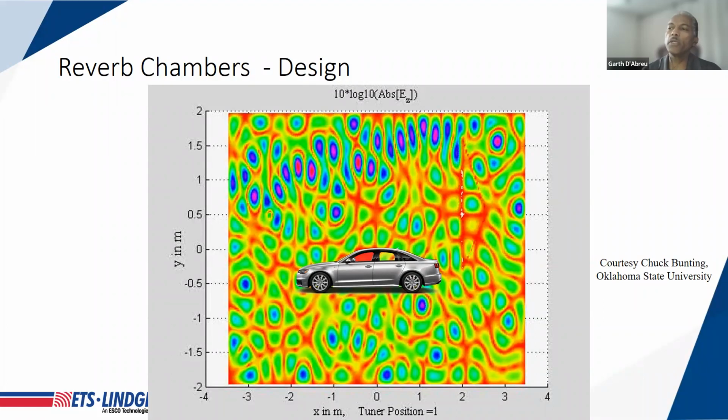If you've got a component that, when exposed to a particular level of RF, would only respond after some fixed duration, or past the expiration of some fixed duration, then that introduces a dwell time to the measurement. And if you're testing in a reverb, it's a little more difficult to make sure that you manage those dwell times adequately in describing or defining how you stir the modes within the cavity.